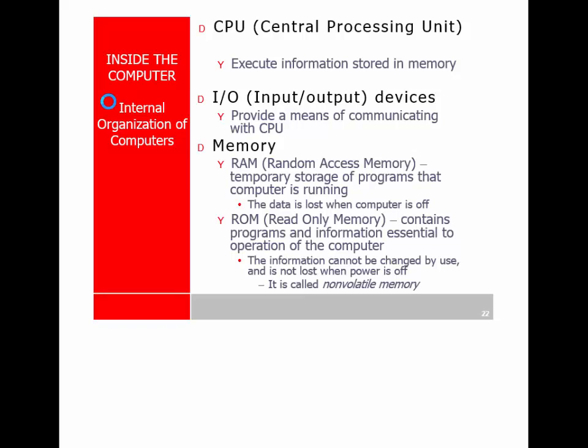When we look at the circuits that we design to access this type of memory, we're going to find that they're the same. They use the same address lines. They use the same data lines. The only difference is there's a line that goes from the microprocessor to the memory called read-write not. When it's high, it's a read. When it's low, it's a write. That's why it's called read-write not.